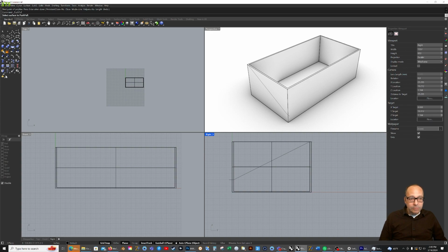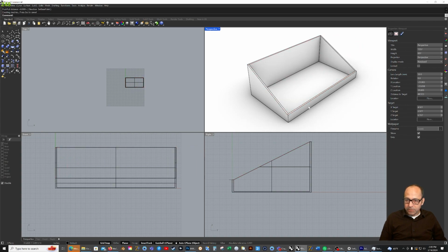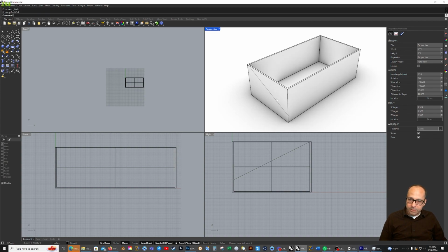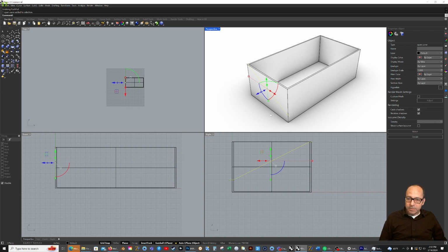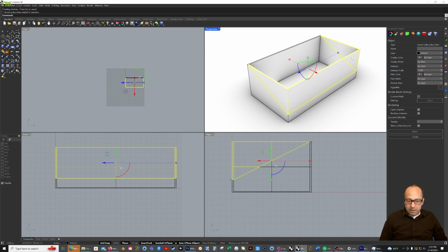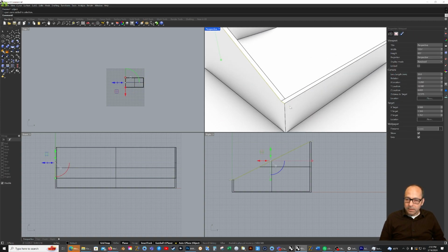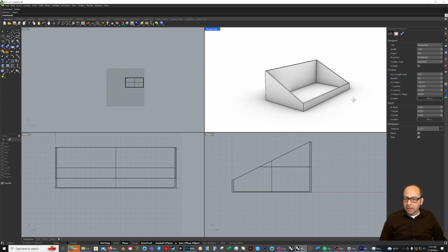You can use the push-pull tool again. Even though this is a separate object, it recognizes that it's on the plane and that that's what you'd want to cut. So if you do this, cut through it and then just delete your little layer here that you used. Or the other option is to click the line. This little line that's part of the gumball is what they call that thing with the arrows. And this is the cut area of that gumball. You just cut through, and then you can just hit delete. So here's our tray.